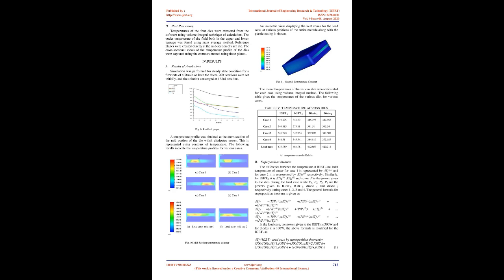4. Results. A. Results of simulations. Simulation was performed for steady-state condition for a flow rate of 4 L/min on both the ducts. 200 iterations were set initially, and the solution converged at the 163rd iteration.